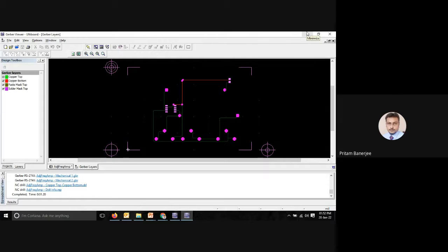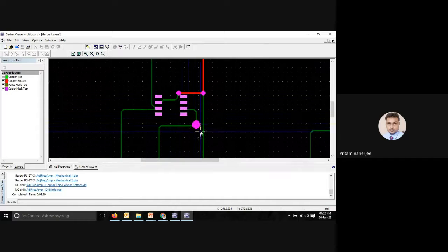So we need to provide all those Gerber files to the PCB fabricator, who will finally fabricate our PCB according to the specific design that we have created. It also has the board outline, what the size of your board will be, where the drills have to be mentioned, what the diameters of the drills are, the distance between each, and every connectivity.